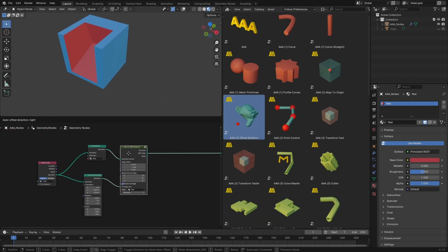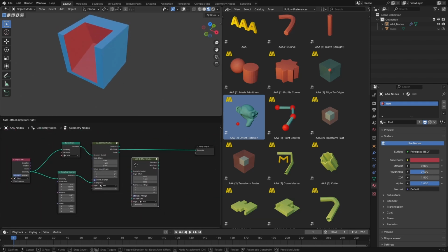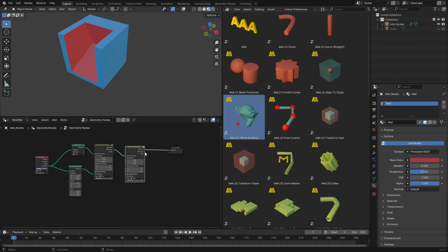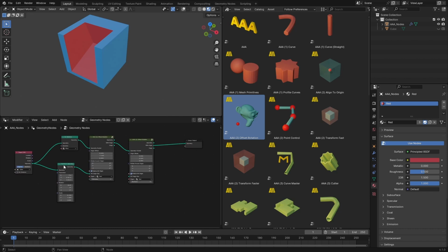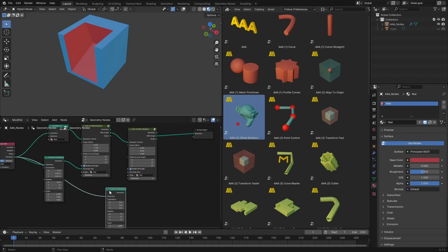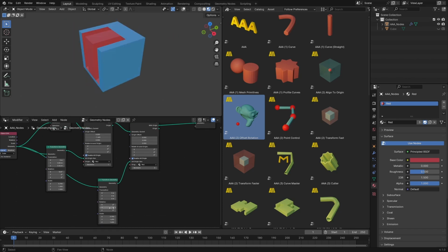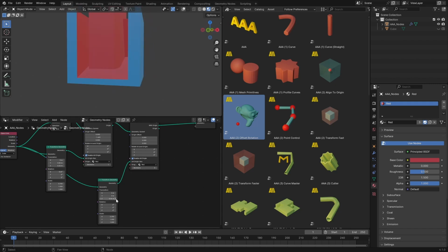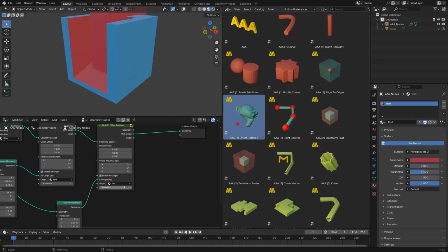Now what you can do, you can just add another one. So you can do this. You can zero out everything, so nothing changes right from the start. And then we can use the new transform geometry 0. I will change the angle, and I already know that I want it to be even thinner, so make it 0.35, and then I can add it here. So now I see it. I will move it up a bit, so I still wanted to cut these. Okay, and then move it back a bit as well. So let's preview it.